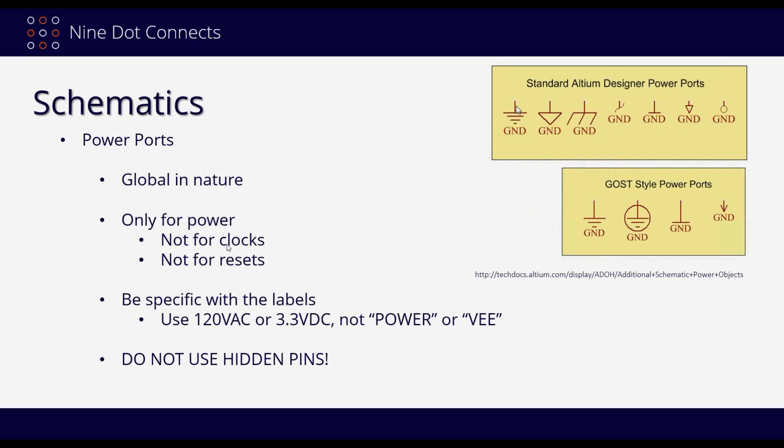Because there's usually a fan-out issue. You may want to put some buffering on your clocks and resets to make sure that there are no major slew issues or just fan-out issues that come along with that type of thing. The key thing I really want to express over here is this concept of the label itself.